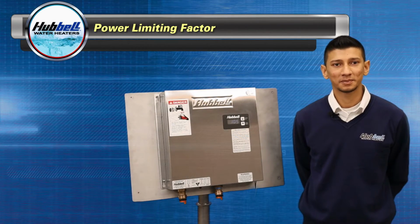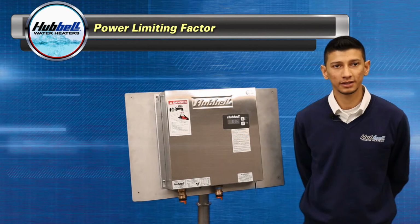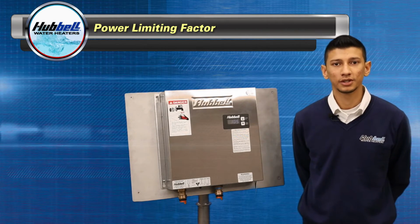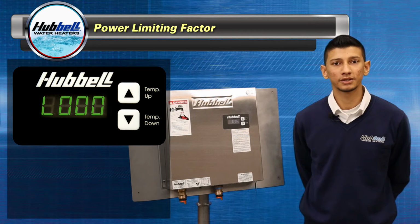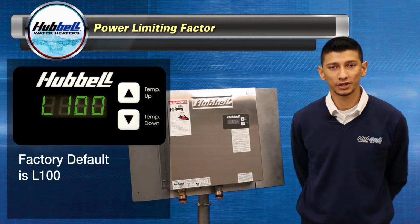The next parameter is the power limiting factor. This allows you to control the total power draw of the heater out of the power available. The range can be set from L00 to L100. Factory default setting is L100.